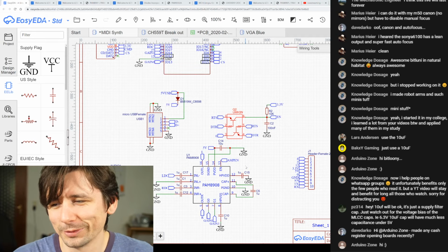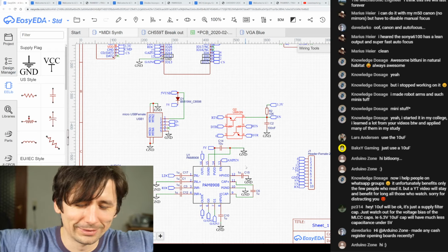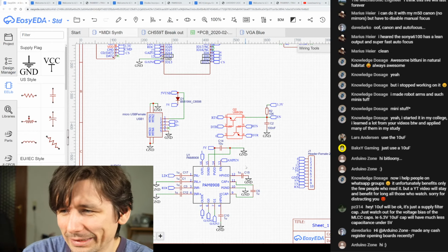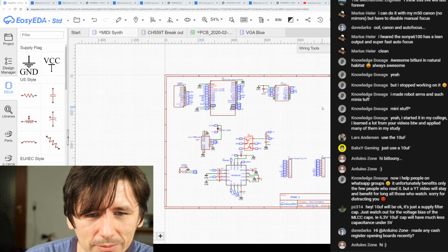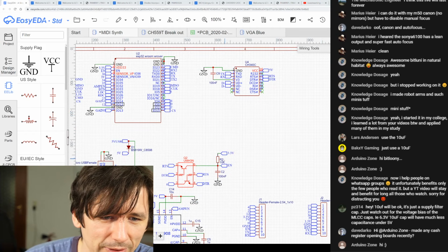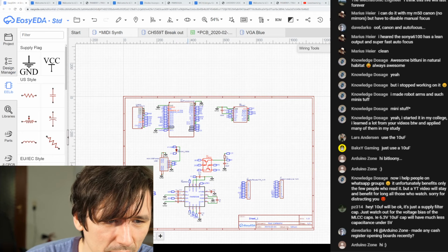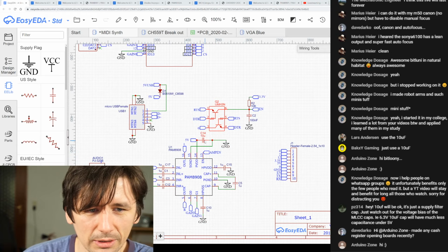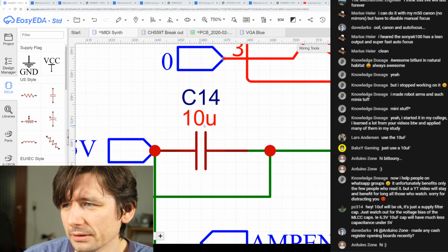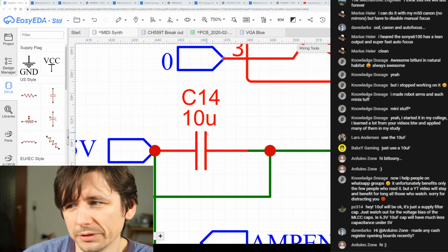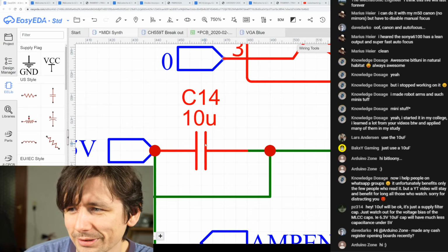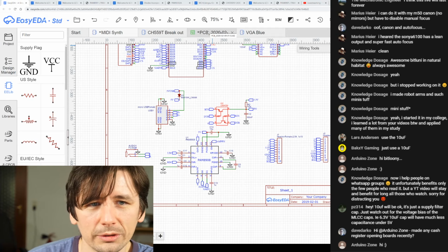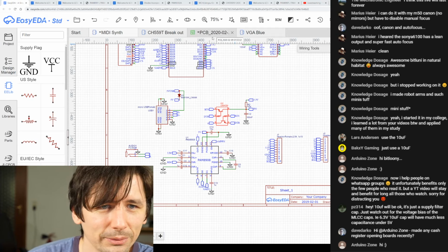There are never exactly 10 microfarads. There's like a 40% deviation or something like that. But I don't see a problem here with that stuff, because there is no oscillator that depends on having the 10 microfarads. So if this multi-layer 10 microfarad isn't actually 10 microfarads but only 4 microfarads, it's still good. It's still better than 2.2. Even though maybe the 2.2 would have a more reliable value.